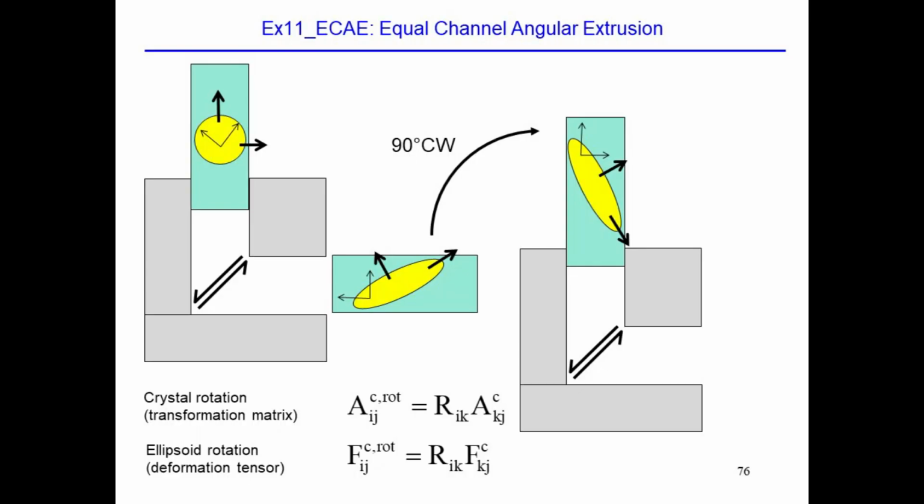So in this case, the material was supposed to retain the same dimension. You introduce your sample in a channel die that has an angle here, and when it goes through the corner of your channel die, the sample shears. Actually, I drew it parallelepipedic here, but it will be sheared. The grain shape will become elongated.